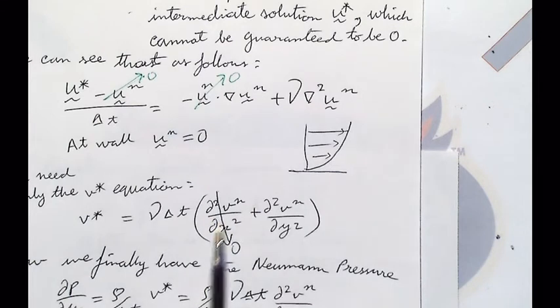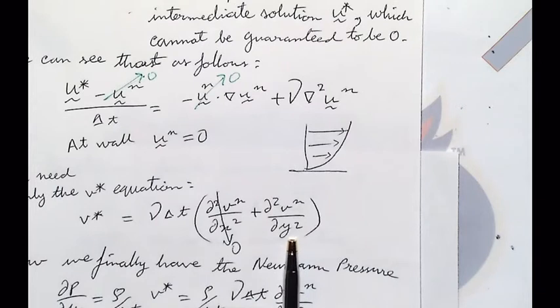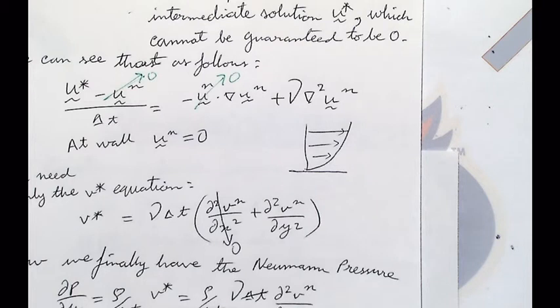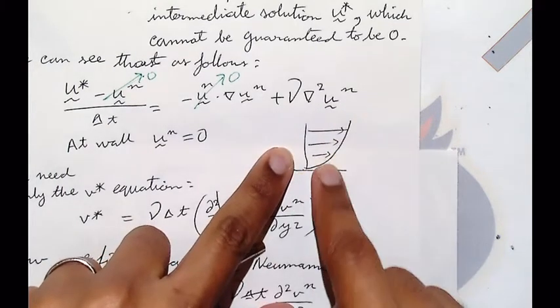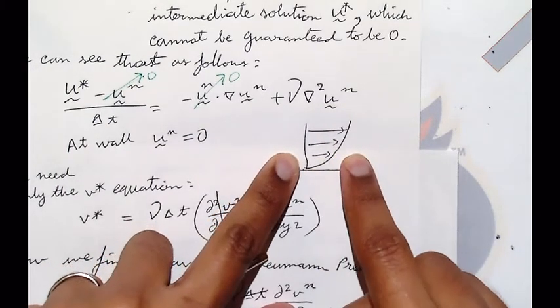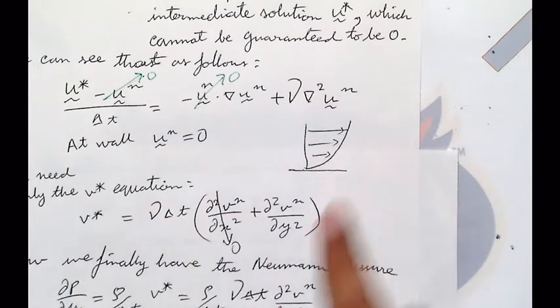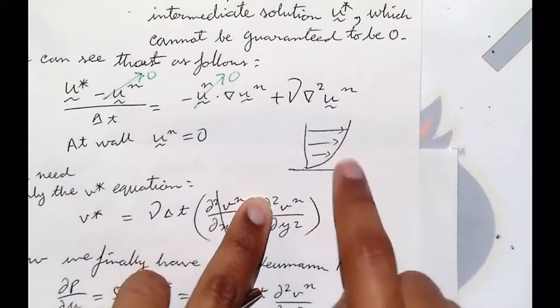This is the V component of velocity. What happens to the U component? Okay, so it's exactly what you were saying. On a flat plate, in the boundary layer, you assume things don't change in X very fast. So you can do the same for U as well. d2U over dx squared would be 0. But Y would not be. This is actually the profile for U, right? d2U over dy squared is non-zero. V is not as straightforward. It's more complicated.